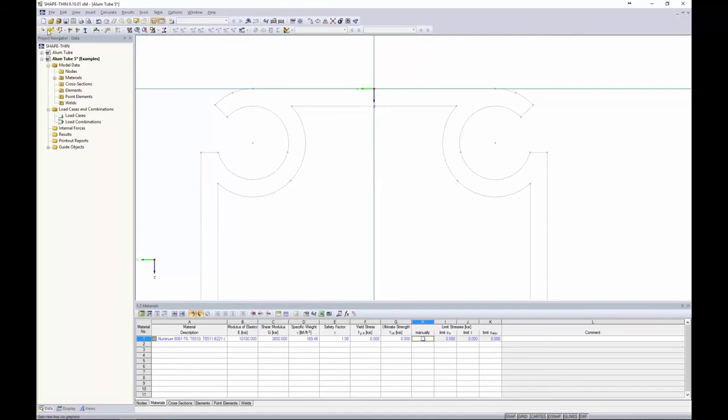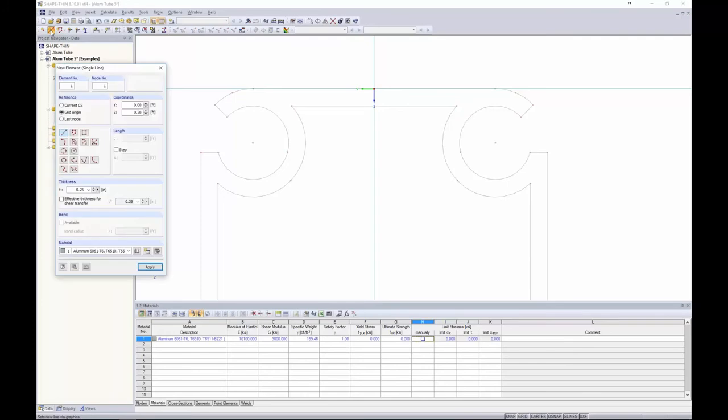Now, the first option we want to go to is this new line up here in our tools. We have a straight line selected here, but I'm going to select a thickness of 0 inches. So all I'm going to do is to snap to one of these points on my arc and snap to the other point that's perpendicular to it. Now, a lot of AutoCAD-like features such as snap points, perpendicular, parallel, that allow us to utilize these features quite nicely.